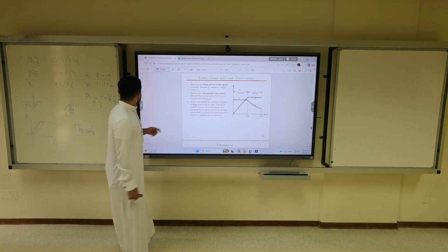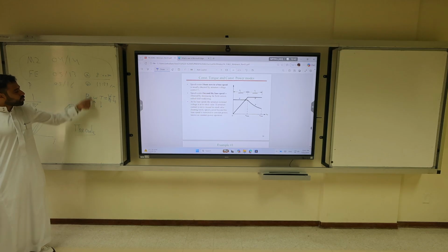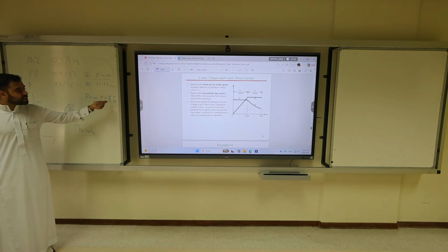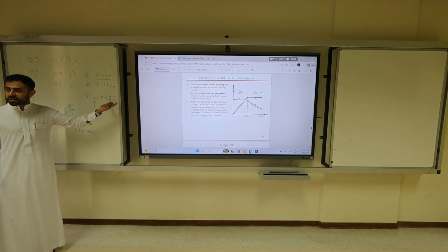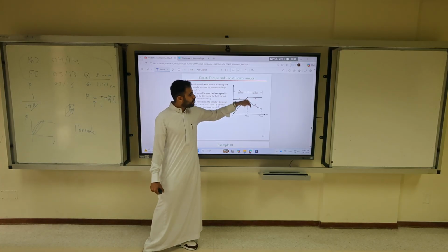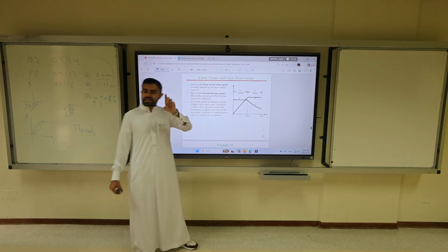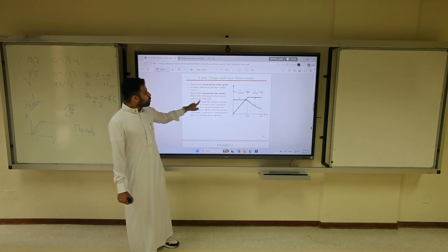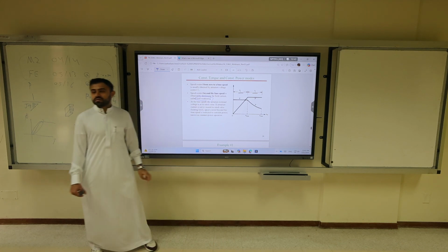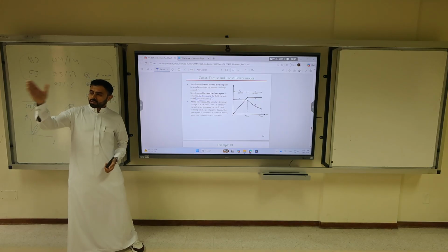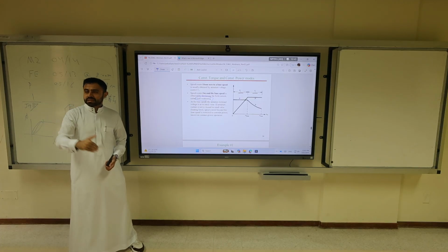So now, if you want to increase omega, you have to drop the torque to maintain the same power, because power is limited by VT IT. It's fixed, constant power. So if you decrease IF, you're going to increase the speed and reduce the torque. This is what we call field weakening. Same as V over F control. Do you remember? After the voltage increase, what will happen to the frequency? You increase the frequency and then your flux drops.